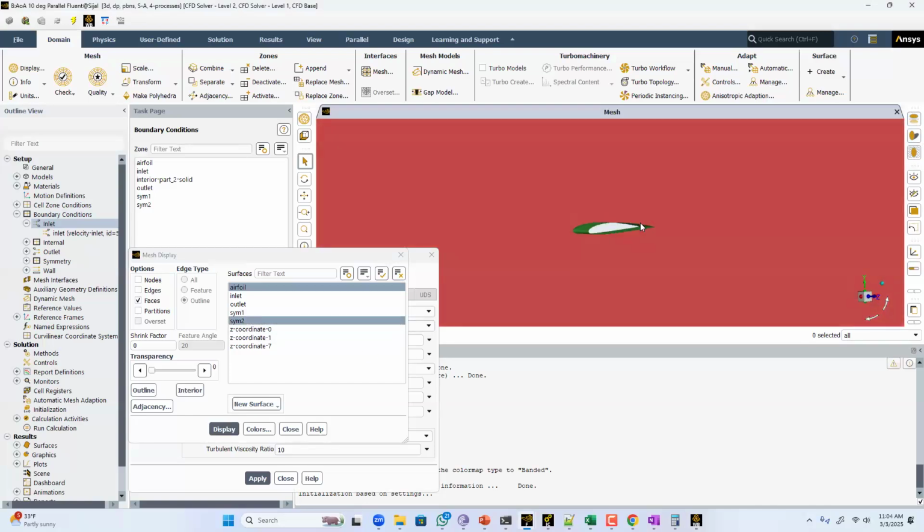Okay, now see that the aerofoil angle of attack is defined this way. This is our chord line. Chord line is joining the leading edge with the trailing edge. And if I provide some angle of attack, that angle of attack is between the air and the chord line. So if I put my aerofoil at some angle like this, it's a chord here, and I put the same flow angle here. Okay, so still I get some alpha there.